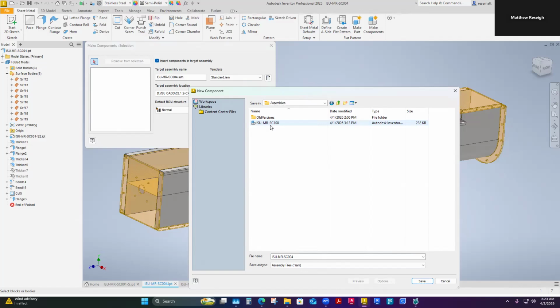Identifying stuff from a number is actually really hard for me, especially in a really complicated assembly. I'm a visual learner, obviously, not that everybody is, and I use my preview window pretty heavily when I'm looking through parts that have similar numbers. I'm like, I don't know what that number is. If I change my assembly numbering to start with 100, at least then I know an assembly would start with a 1. That would be a cue. So there are some numbering strategies I could use to look at a list of numbers and know that the 100s are assemblies.